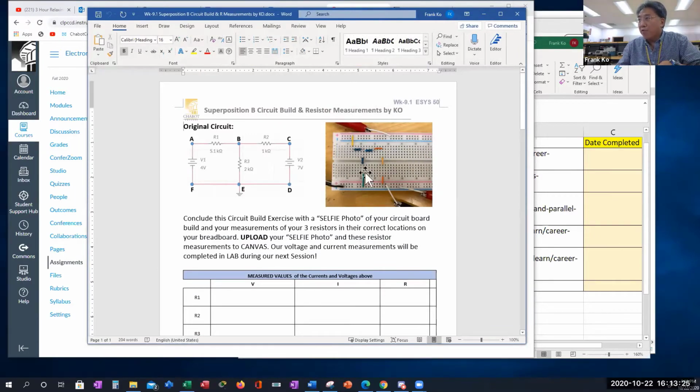So you happen to have a circuit build that shows how you need to build it. And as it turns out, remember we had 3 green wires that were hanging on this side of the board, 3 green jumpers. We don't need those green jumpers. The green jumpers would have been appropriate if we were using your breadboard power supply, this little power supply right here. If we were using this guy, we would have used the green jumpers. And so I didn't remove the green jumpers when we were in lab. And so what it is that you have is a cleaner build of the board.